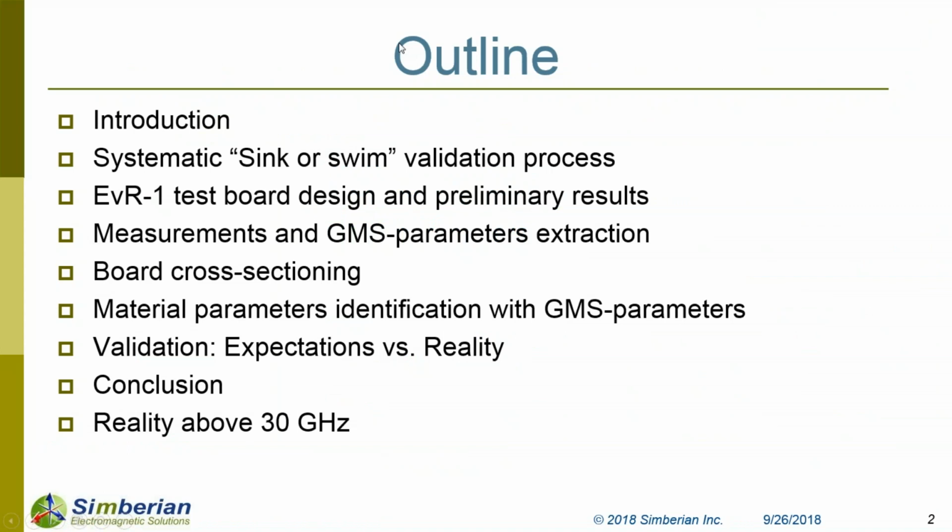So, the outline for today's webinar. It's a brief introduction, a description of the systematic Simbeor validation process, and the EVR1 test board design. EVR stands for expectation versus reality. That's how we named our validation board. I'm going to speak about the measurements and generalized model parameters extraction. We'll come to board cross-sectioning. From there, Yuri will speak about material identification using GMS parameters, validation, conclusions, and some things we found that happened above 30 gigahertz.